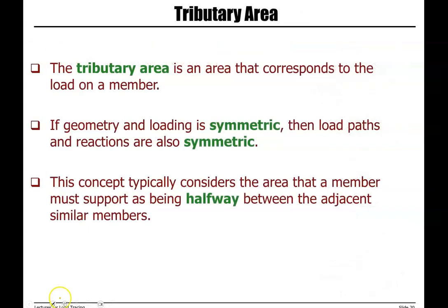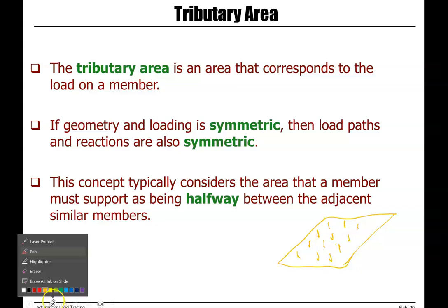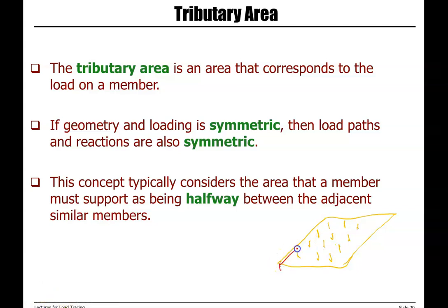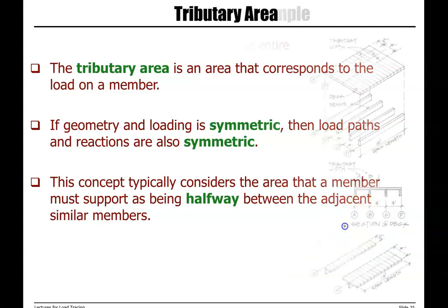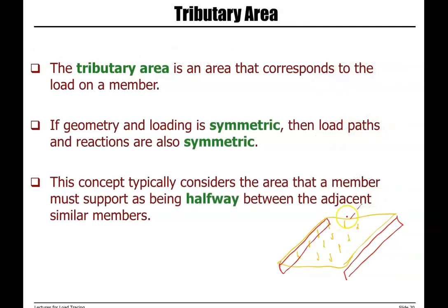This is the example that I talked about earlier. So if we have a surface with area load and then it's supported by two beams, the load is divided. Half of the load is carried by the right beam, half of the load is carried by the left beam.